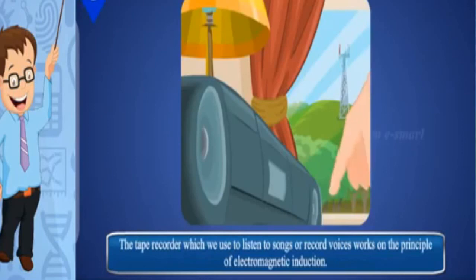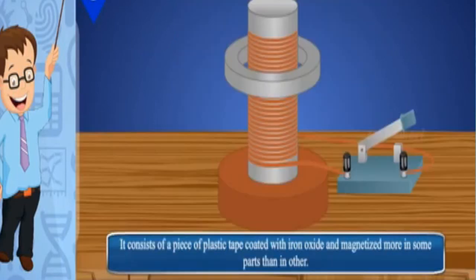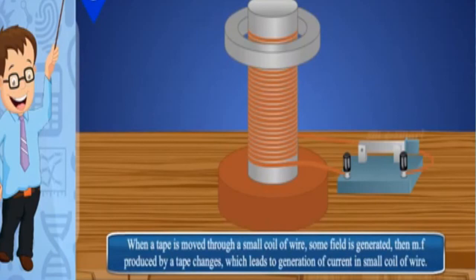The tape recorder which we use to listen to songs or record voices works on the principle of electromagnetic induction. It consists of a piece of plastic tape coated with iron oxide and magnetized more in some parts than in others. When a tape is moved through a small coil of wire, a field is generated. Then the magnetic flux produced by the tape changes, which leads to generation of current in the small coil of wire.